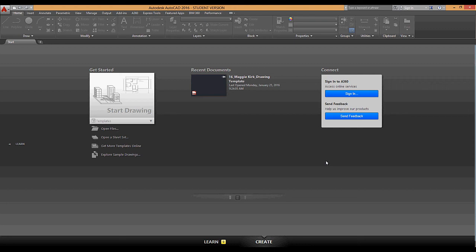So we're going to talk about templates a little bit more and setting them up now with adding layers. Layers are a way of keeping your files organized and for you to maintain an overview. AutoCAD has the option of creating layers and drawing objects on and assigning objects to layers. Layers are basically categories to contain objects of a common type.